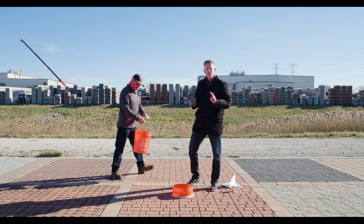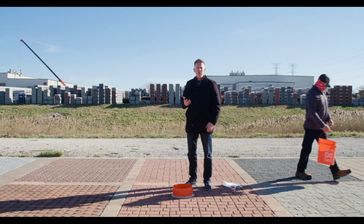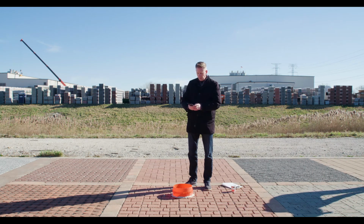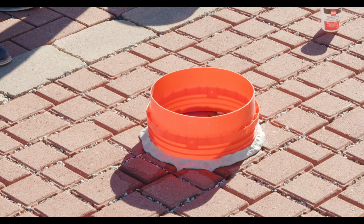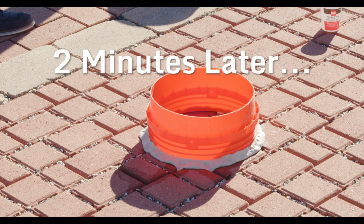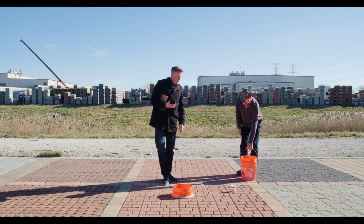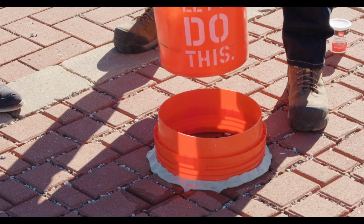So now we're going to wait 2 minutes for this to drain, and then we're going to pour 40 pounds of water on the surface since it drained in less than 30 seconds. So I'll start my timer here for the 2 minutes. All right, now that our 2 minutes is up, we're going to pour the 40 pounds of water, and I'll start the timer once the water hits the surface of the pavers.